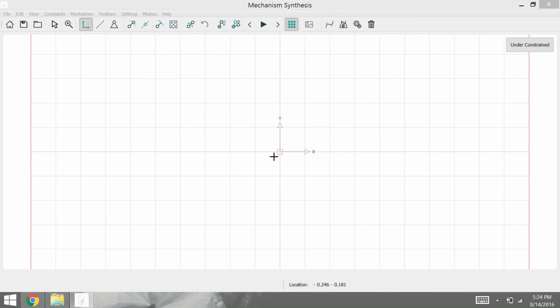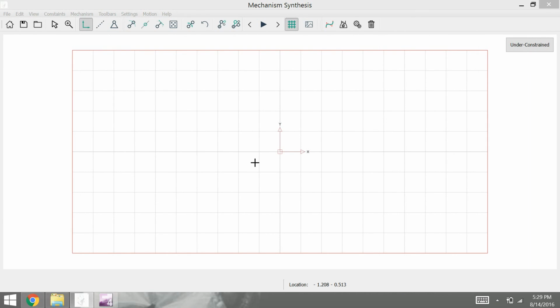So till now you might have understood that we need at least 5 constraints in order to get finite solutions. That might be in the form of 5 positions or 3 positions or 2 pivots or any combination, but we need at least 5 constraints in order to get a finite solution. If you have less than 5 constraints, we get infinite solutions. To tackle that problem, we are using the next feature called motion synthesis. Consider the example of 2 positions. For 2 positions we are lacking 3 more constraints, thus we will get infinite solutions. But to get the best solution out of that we are using a screw motion algorithm.